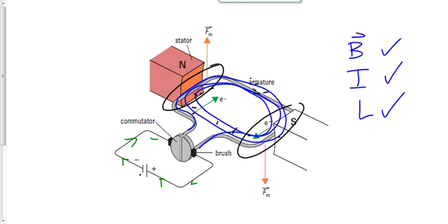No, it wouldn't. It has to have that because you need to reverse the current there. There are other designs of motors that you can make work, but with the scenario the way it's set up here, no. If you took away the split in the ring, and this was just all a conductor, what would happen?